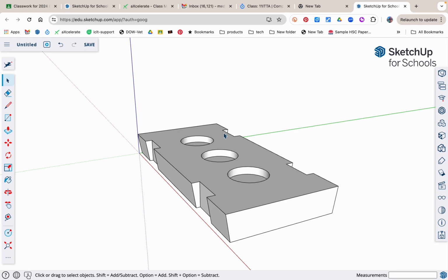We're going to use this block as a reference point, but make sure when you do that you don't have this in edit mode. I'm just going to use it as a reference. So if you've got it open like that, click off it, press R, go to the corner, click and drag, and type in 40, 40. So we have a square that's 40 millimetres square.